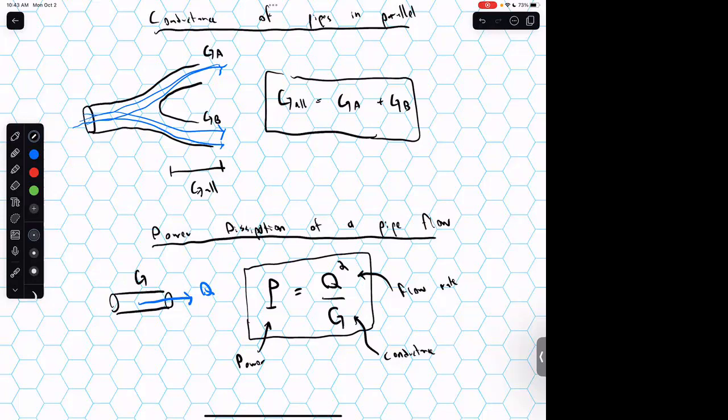So this tells me a couple of things. The biggest one is that if I'm trying to move a ton of fluid through a pipe, the more fluid I move, the more power I'm going to have to expend. So whatever generator I'm using to build my pump that forces the fluid through the oil pipe, the amount of power I'm going to have to dump in is going to increase super quickly. And this is what makes it so expensive to move large amounts of fluid long distances. And it scales quadratically, so it's a very sharp increase.